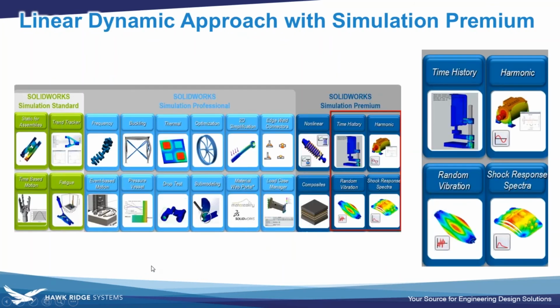But now looking at this nonlinear study, if I were to look at some of my parts, now when I go into the material definition, we're not using a linear elastic material. We're now able to define this plasticity von Mises, where it allows us to define this stress strain curve. And again, I utilized a material that was from our material database, where if I had something a little bit more unique, I could have created a custom material.